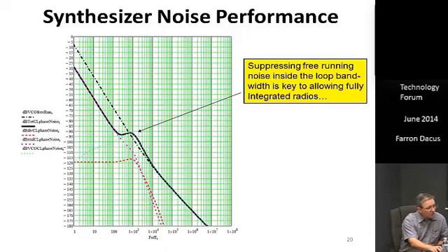Far out, the noise is rising at 20 dB per decade. As you get a little closer in and start seeing flicker noise in the active components in the VCO, it'll generally transition to 30 dB per decade. And you can predict this noise if you know how.